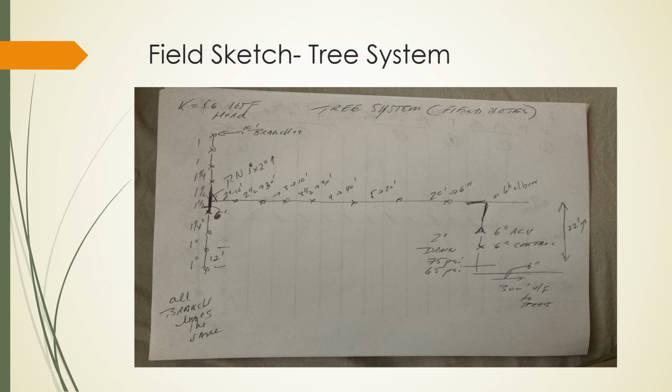So you've got to do that and you've got to be accurate in that. And then I just start to work backwards using the reducers. I grab there's 10 foot of 2, then there's 2 1/2, and then there's 3, and I just work my way backwards along that cross main until I've got a system.